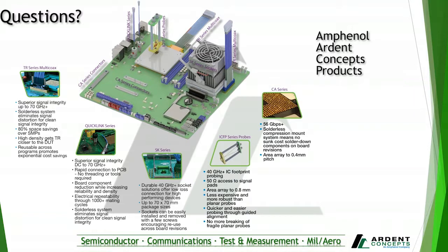What care or maintenance is required for the CA connectors and interposers? We often recommend that our customers institute their own preventative maintenance plan. This will guarantee the longest life possible of the connectors. We have results that show that our CR contact set can hit 1,000 mechanical cycles repeatedly, and this is probably conservative. We do have customers using that CR contact set out to multiple thousand cycles, but we want to be conservative with that 1,000 cycle rating. We've tested our spring probe contact sets out to 10,000 mechanical cycles. And so, where you're going to be expecting a high cycle count, a solid preventative maintenance plan is really encouraged.